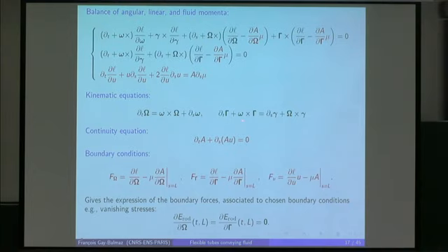And so this is angular and linear momentum, fluid momentum. In addition, we have fluid mass volume conservation, the continuity equation for the mass density of the fluid. And what in addition the principle gives is directly the expression of the force at the boundary exerted by the fluid leaving the tube.